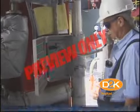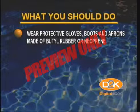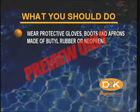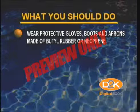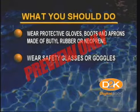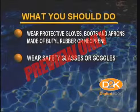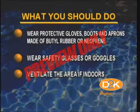What you should do: wear protective gloves, boots, and aprons made of butyl rubber or neoprene or other materials specified in the MSDS. Wear safety glasses or goggles. Goggles are often better protection against liquid splashes and airborne dust than glasses. Ventilate the area if indoors.